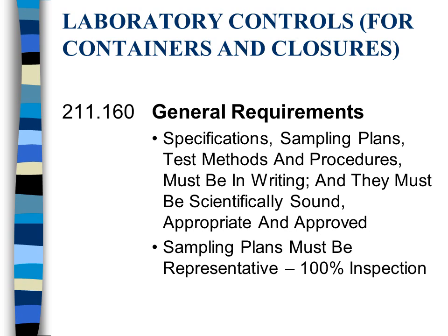If that cylinder fails, it becomes what we call an out-of-spec procedure, at which time the QCU member will get involved. And there is a procedure to determine whether or not the analytical equipment was out of calibration or that particular lot failed. One cylinder represents the whole lot. If that one cylinder fails, that whole lot fails. Needs to be blown down, re-evacuated, and refilled.